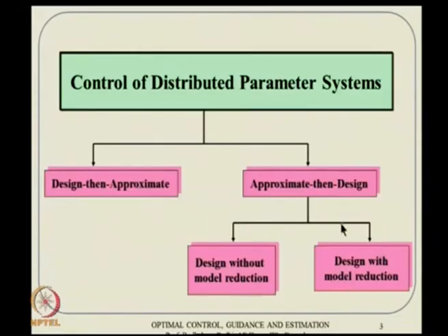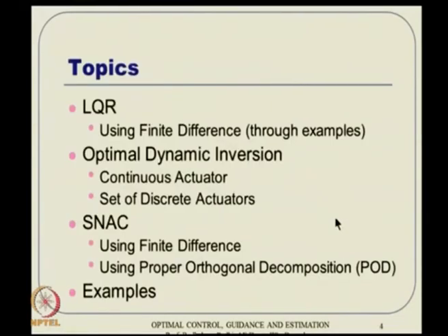Okay. So, this is how it is, and the topic that these two lectures typically will talk about is LQR design. Okay. So, if the system dynamics happens to be linear, that means the PDE itself is linear, then it will result in an approximate lumped parameter system which is also linear. And the cost function is quadratic, then it also results in a finite dimensional cost function which is also quadratic. So, that will have a compatible LQR formulation, and hence because we know LQR formulation, we can go ahead and implement it actually, and solve it and implement through the Riccati equation, all that.